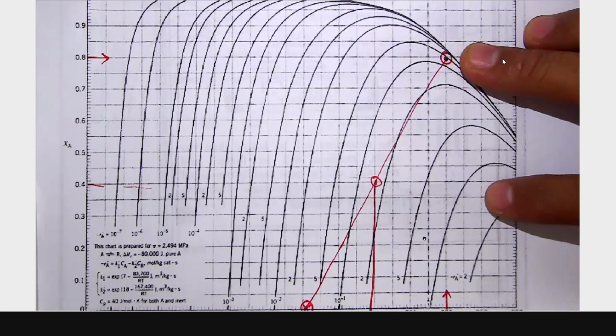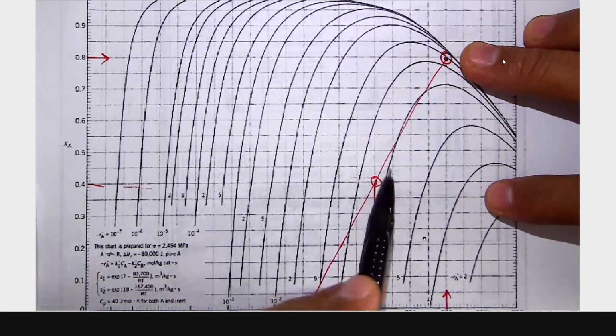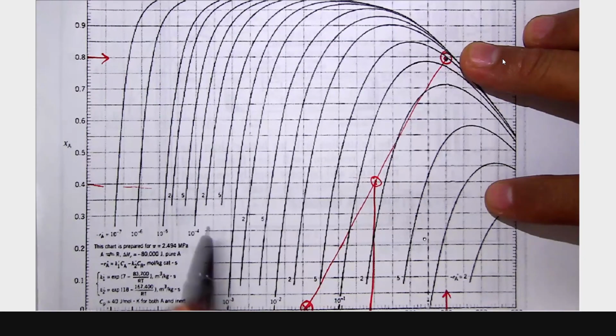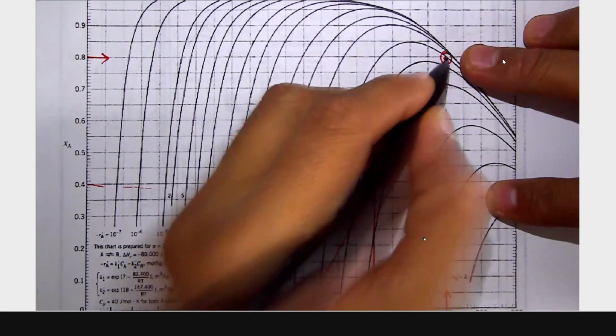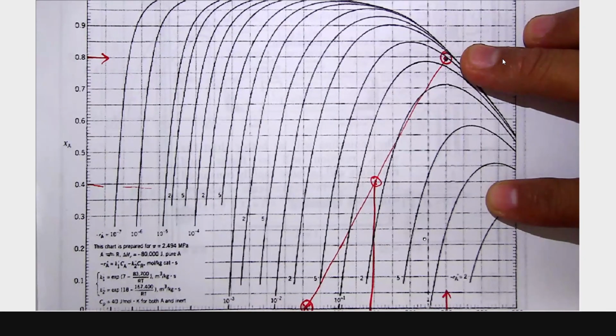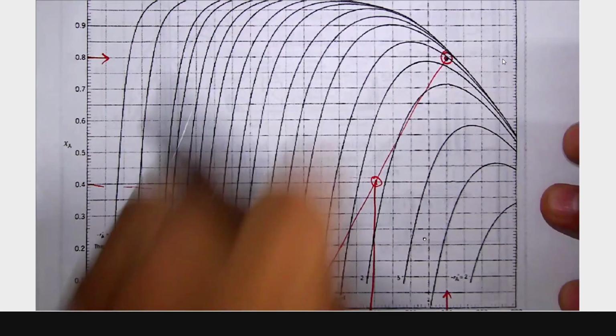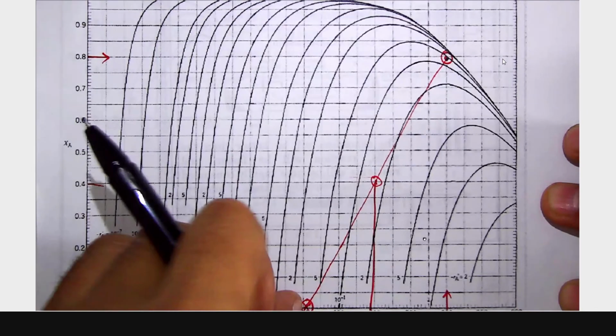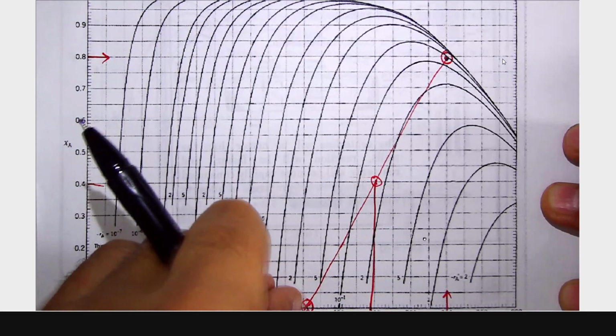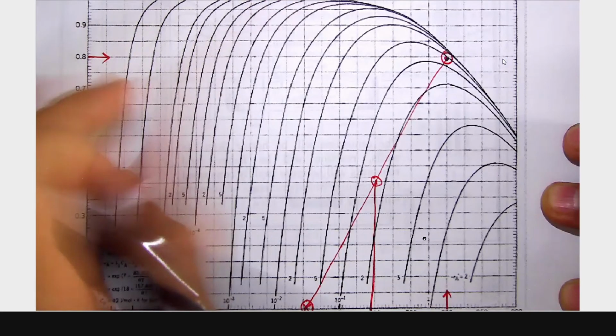You see the slope? Slope is 1 upon 250. So you can draw the line, and you'll get the line which intersects at 600 degrees. That means your operating line is this one. So in the reactor, it will start at 600 and then reach 800 with 0.8 conversion.